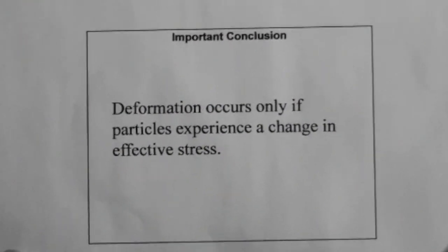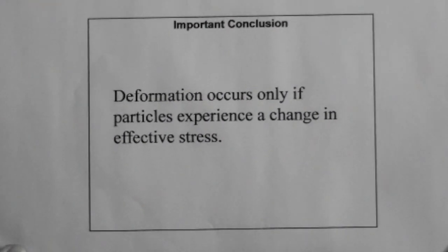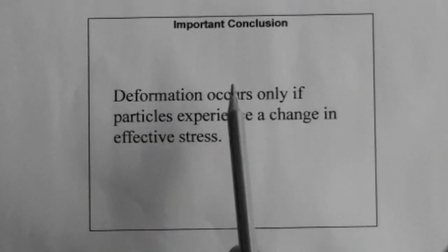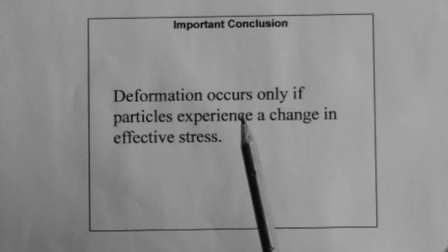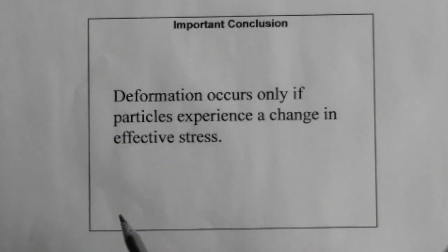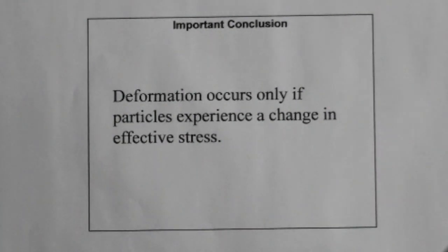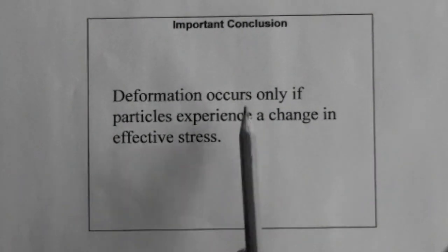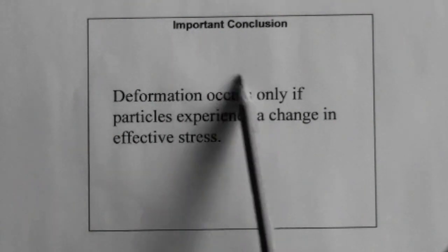That is the key to everything, actually. Because there is a change in effective stress, that is what leads to consolidation. So the deformation of the soil can only occur if the particles feel a change in the stress that they feel, right? So this here is very important to understand, this summary.